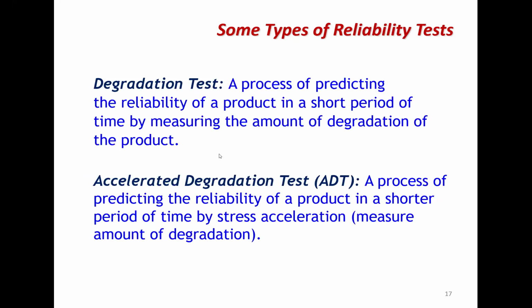Well, of course, people think, okay, if I am more aggressive, even though I cannot collect the failure times under normal operating conditions, if the product degrades, for instance, the strands of a material degrade, and a crack initiates and keeps growing in a mechanical part, as long as I can monitor such so-called degradation data, we do not have to wait for the product to fail. So I can still collect the degradation data and build a degradation model to predict the reliability of the product or the device. So this is the concept of degradation testing.